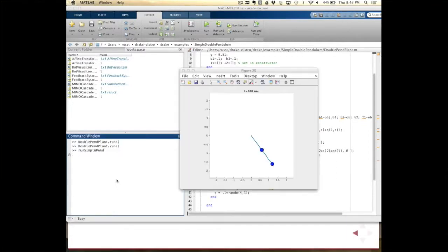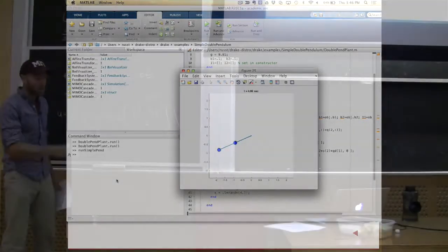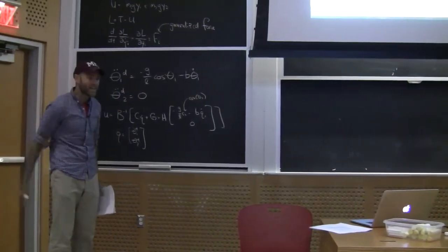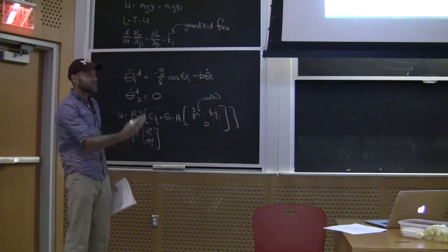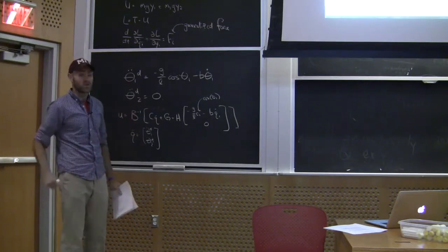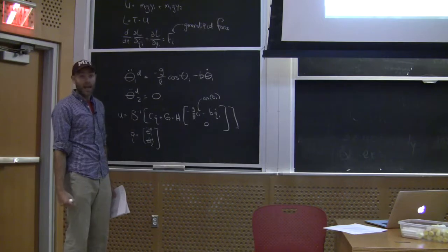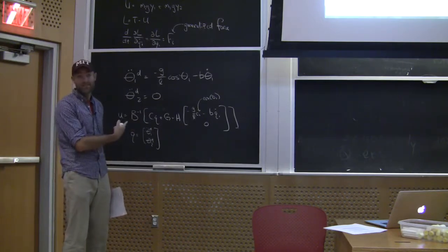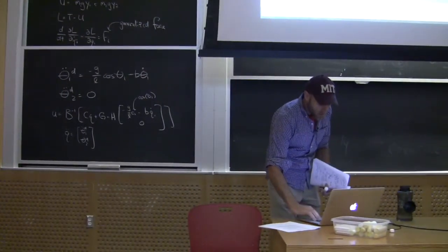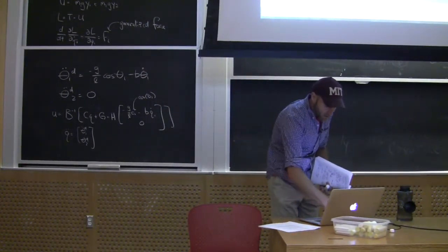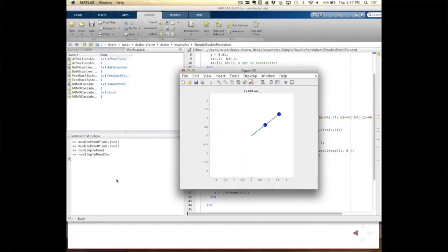Okay, and assuming I started with theta double dot equals 0, since I didn't stabilize it here, then it's going to act like I've just replaced the dynamics. I've taken my beautiful second order 2 degree of freedom dynamical robot, turned it into effectively a 1 with just using high gain feedback, right? Those motors are potentially doing a lot of work to make that happen, but the math is easy, right? In fact, I could do the same thing if I just flip the sign of gravity, right? Then I could even make it look like an upside down pendulum, right?